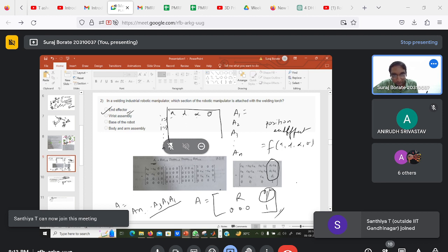So this is when the DH parameters are given. A robotic company will have to give specifications of its robot, right? It will not give you the matrices. It will just give you the DH parameters, the table. From the table, you know what the link length is, or what the offset is, what the twist in the links is. So you know the workspace of the robot by just multiplying these matrices.